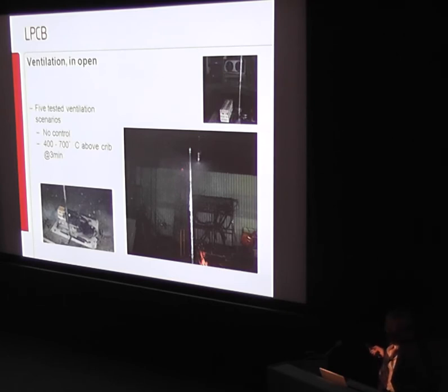But equally, with ventilation, most of the drops actually get blown away. In all our tests in the open space, we had no control. The fire continued to burn every time, and that's with the fire directly underneath the nozzle. So ventilation, I wouldn't say we've done it completely, but it really is a significant factor, and that has to be understood by all.